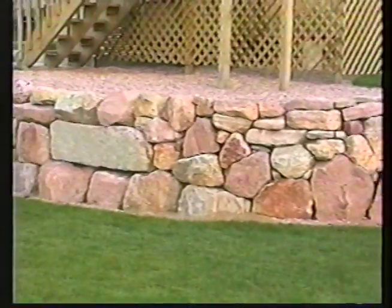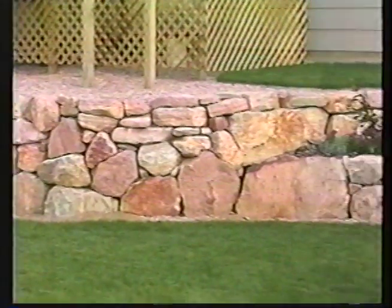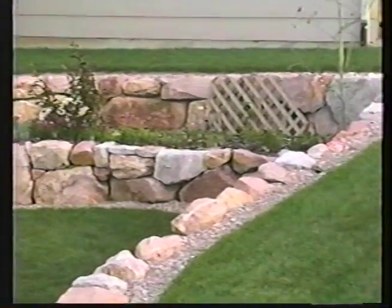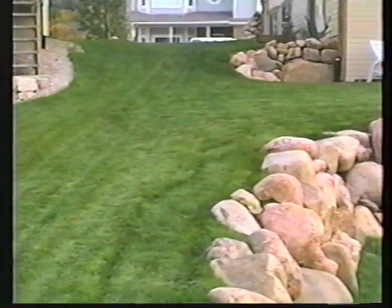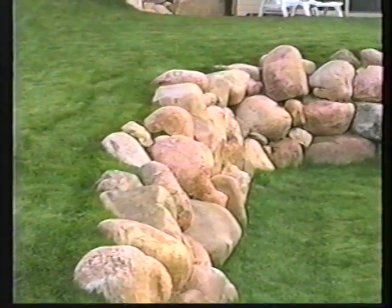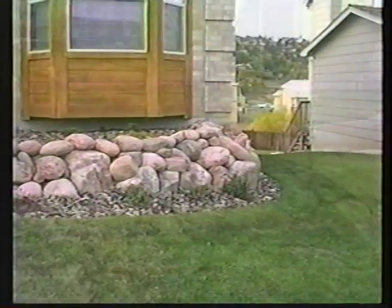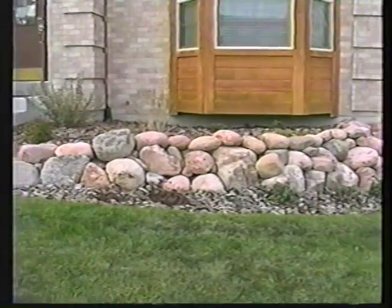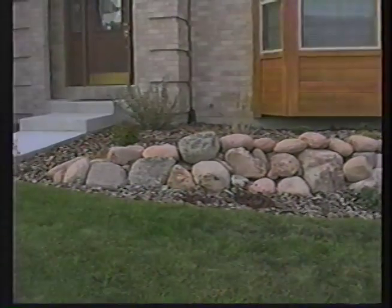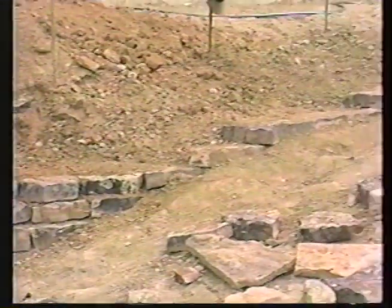The second category includes different types of boulders. You will generally find that the choice will be between an angular boulder or a more rounded one. When making your choice, consider the height and length of your wall. For walls 3 feet or over that are retaining significant weight, we recommend that you choose larger boulders. For lower walls, smaller boulders or one of the flat rock types may be more appropriate.